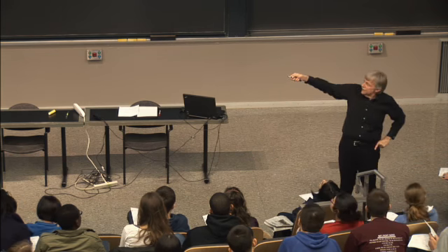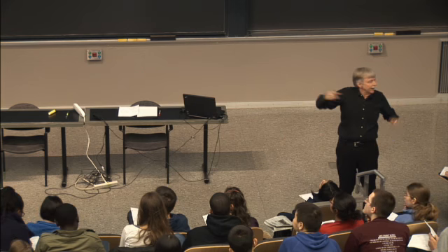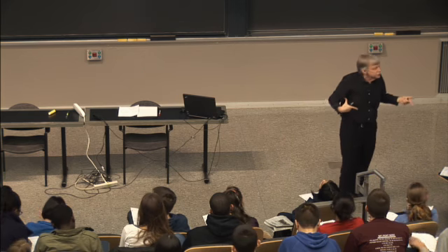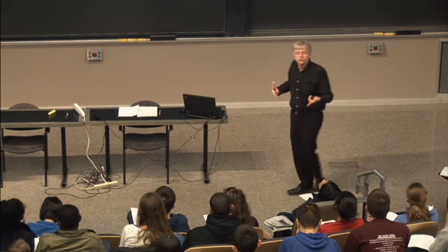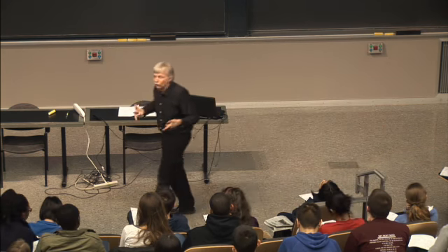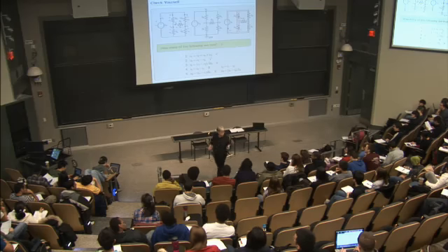You can reduce the number of unknowns by using something like node voltages or loop currents, and that gives you fewer equations to solve. They're completely equivalent. They look a little different.